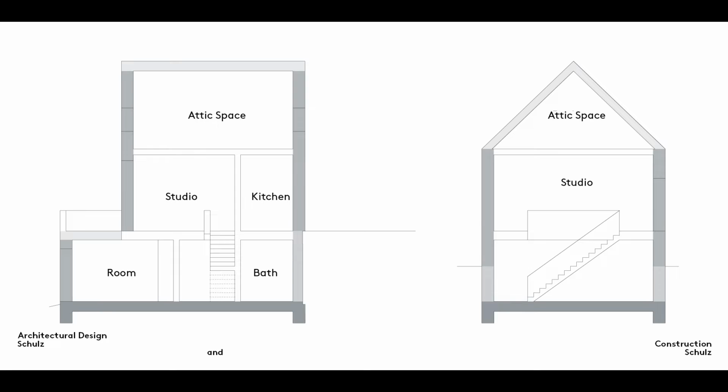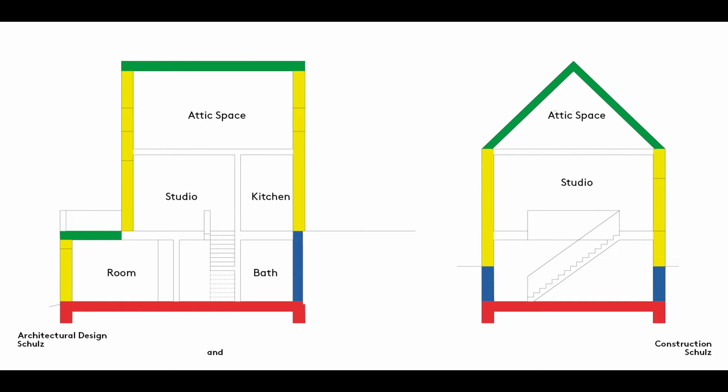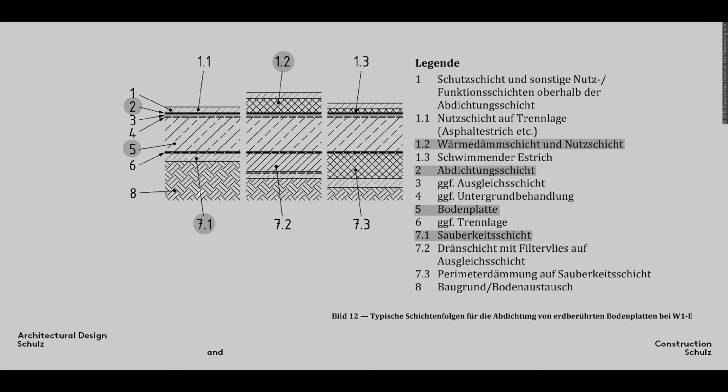In broad terms, these areas are the base of the building, comprising the foundations and floor slab, the underground exterior walls, the overground exterior walls, and the roof. In buildings of more complex geometrical design, overground floors, such as those over archways, for example, constitute another category. We have already explained the makeup of the base of a simple building in the films in our Foundations series.